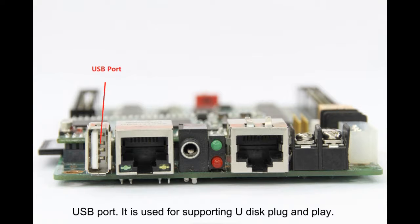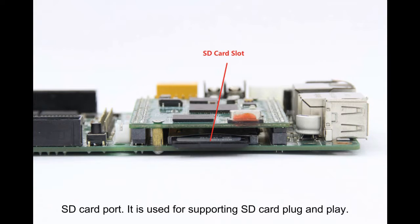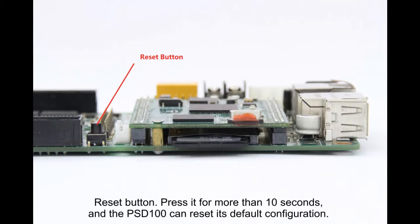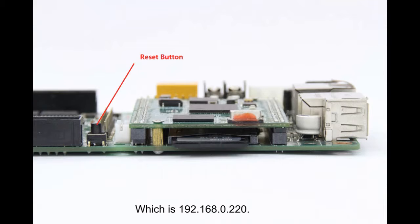USB port is used for supporting U-disk plug and play. SD card port is used for supporting SD card plug and play. Reset button. Press it for more than 10 seconds, and the PSD100 can reset its default configuration. Usually it's used to restore its default IP address, which is 192.168.0.220.